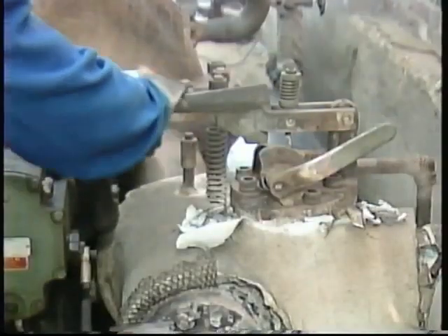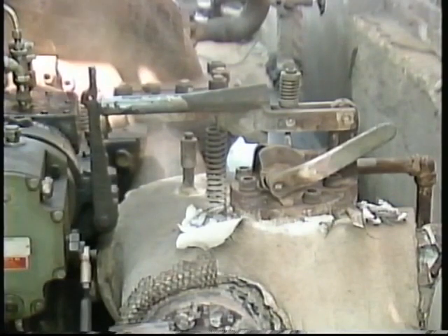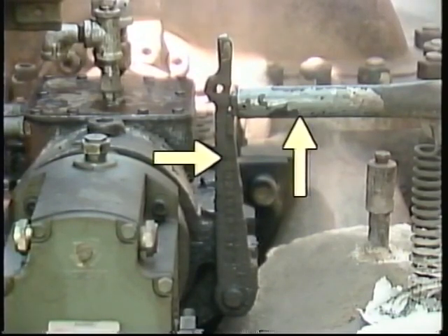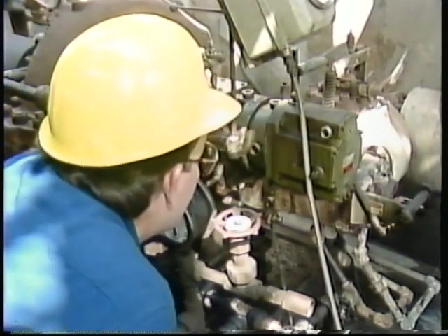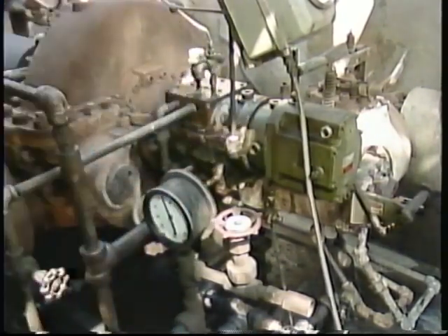Look it over for any signs of damage. Make sure that the overspeed trip mechanism has been reset and is in good condition. The trip latch should hold the lever in place to keep the trip valve open until triggered by an overspeed condition. The governor, too, is a vital part of the turbine's control system and ought to be included in your pre-startup inspection. Check the lube oil level for the governor and replace or replenish the oil if necessary.